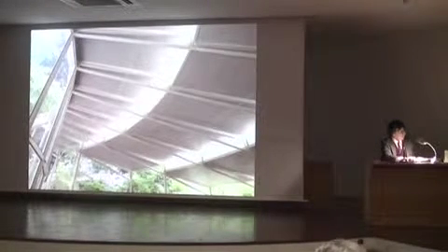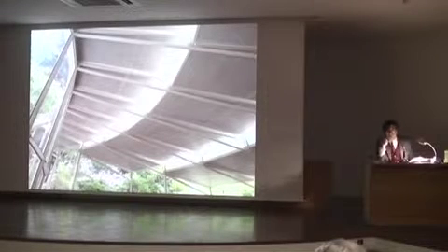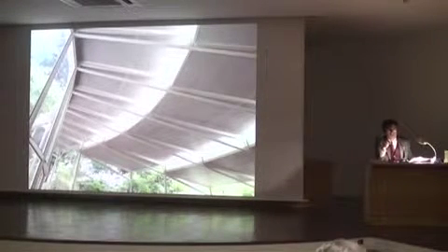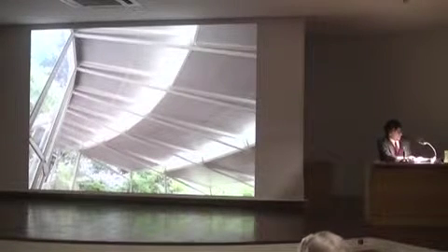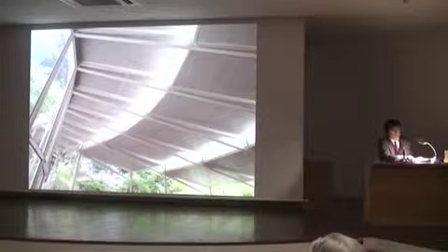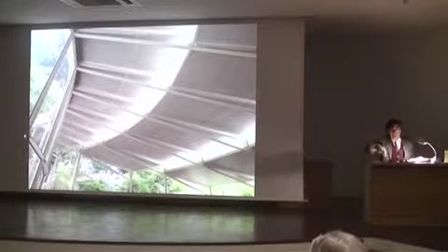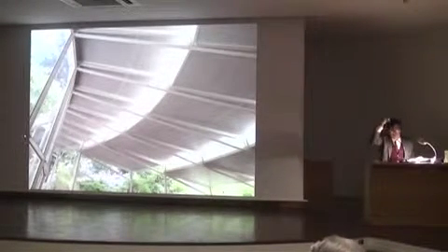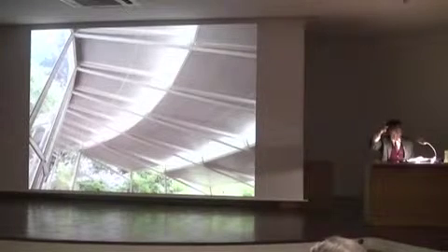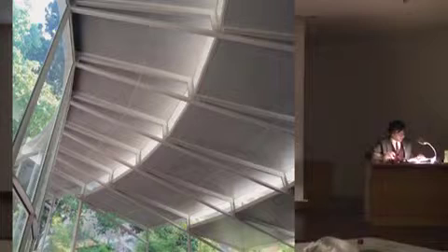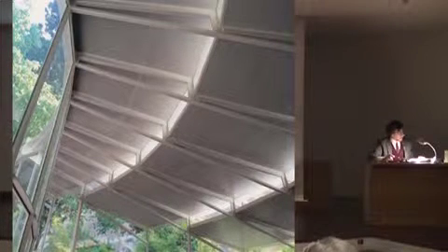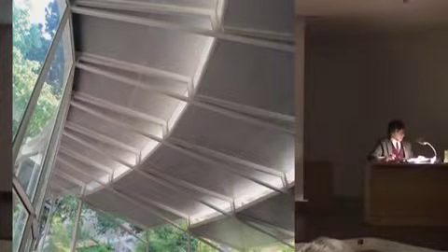And now we will see the pillars that support these frames. Again, tubes of 4 centimeters, 7 or 8 meters high. We have like an intermediate strap that divides the glasses in 2, otherwise it would be 7 meters high. So this is the strap that links and prevents the mini pillars from warping or buckling. The mini pillars are 40 centimeters.